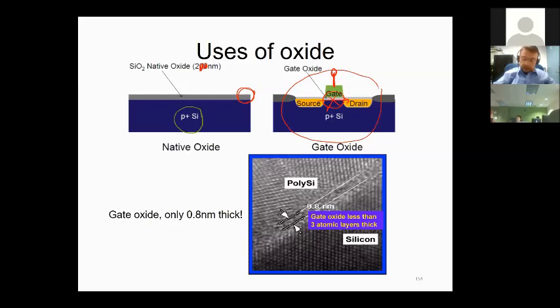And the importance is, here is another electron microscope image. So you can see the thickness of the gate oxide here. It's only 0.8 nanometer thick, or 8 angstrom thick. So we have the gate as the polycrystalline silicon in this case. So I can see some arrangements of the atoms, but it's not going to be like the crystalline silicon where I will end up with what we call the grain boundaries. As for the silicon, I have a fully nice arrangement here underneath. And here I again end up with the amorphous material that I was emphasizing.